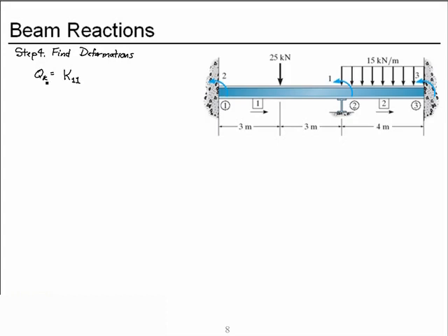They're the applied forces directly to the degrees of freedom, equals the portion of the structure stiffness matrix that is the forces at unconstrained degrees of freedom due to deformations at unconstrained degrees of freedom, and those deformations are given by capital D sub U, and to which we add the fixed end forces at the unconstrained degrees of freedom.